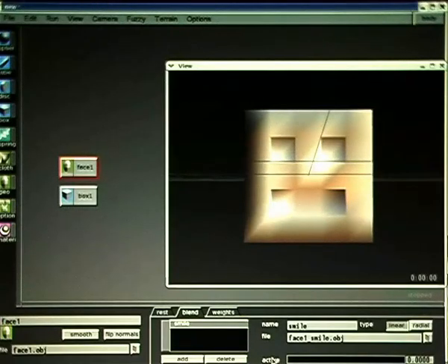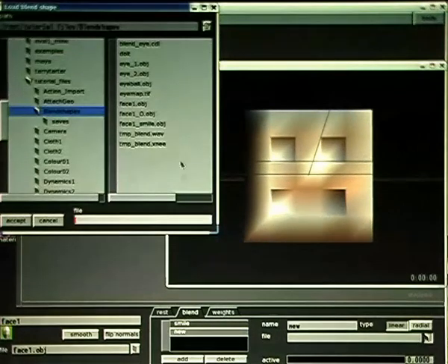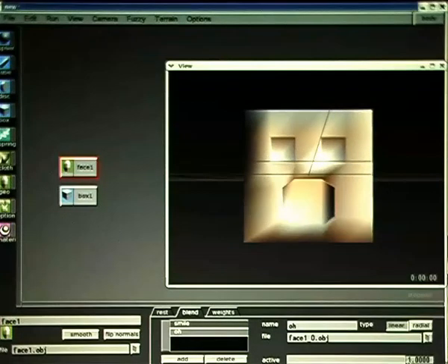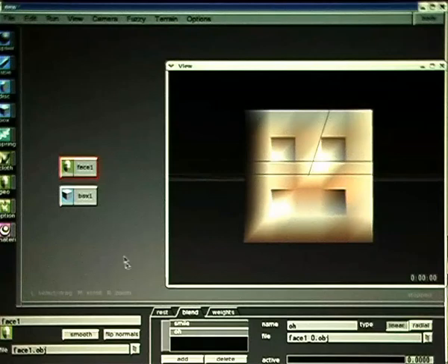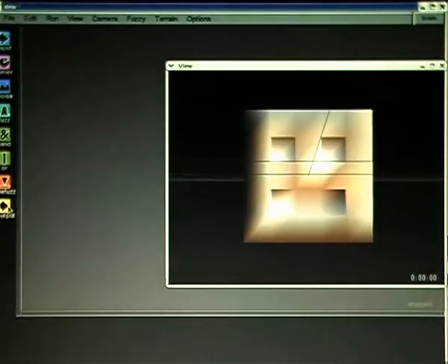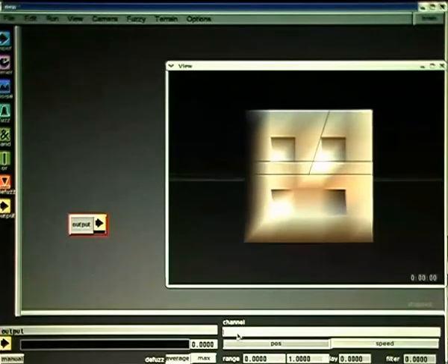Let's also give it another facial expression, so click Add. And we also have face1_O. We'll call it O. And this causes the face to go O. Now, it's not very useful if it can't be accessed in the brain, but it can. So we go page up to the brain, create an output node, and put in a channel face1, that was the name of the geometry node, :smile. And that's the name of one of the blend shapes.